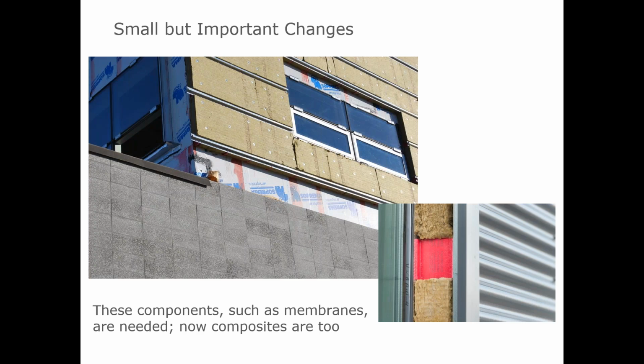Well, as energy codes require more and more performance out of the same assemblies we've built, there's going to be more of an introduction of composites, plastics, fiberglass, rubber, let's just collectively say composites, non-metal stuff, in our non-combustible building assemblies. These changes are occurring because they trigger much, much greater insulative efficiency from these assemblies, these walls and these windows, and they're present to reduce the heat flow that would otherwise occur if those components were the more traditional metal sizes and shapes and styles. So just like the membrane was used for the necessary performance that we demand from it, and it happens to only be possible to provide a combustible component there, so too will composites become introduced.